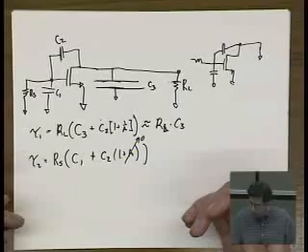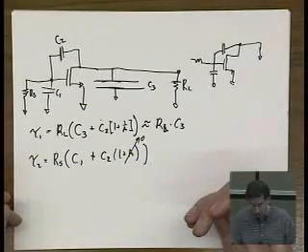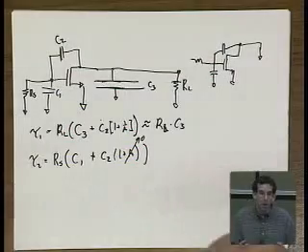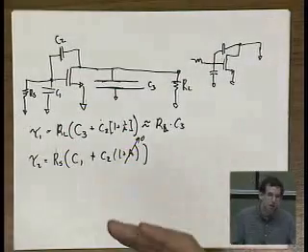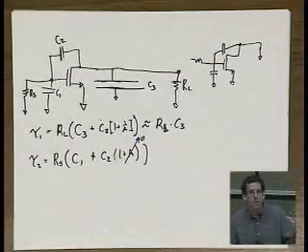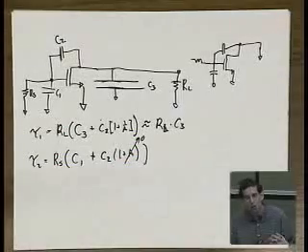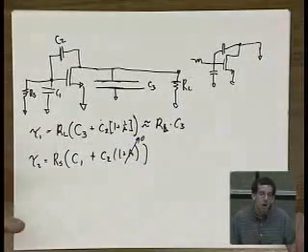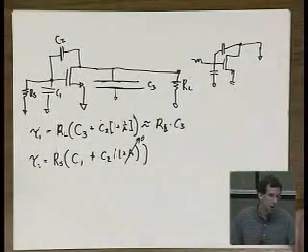And that's actually a really good segue, but I'm going to hold off on it for 10 minutes because I wanted to talk about something else. So in the intermediate case, where all the capacitors are roughly equal and the Miller effect doesn't dominate and you can't tell what the dominant pole is, do a zero value time constant analysis.